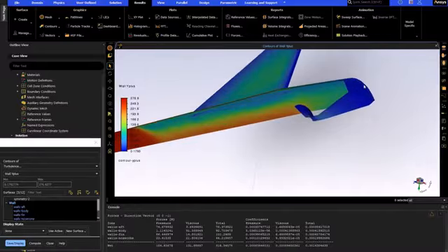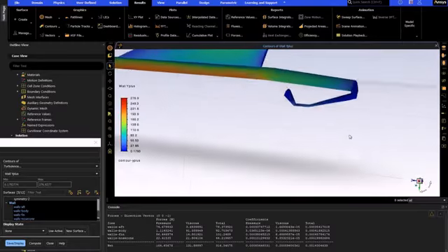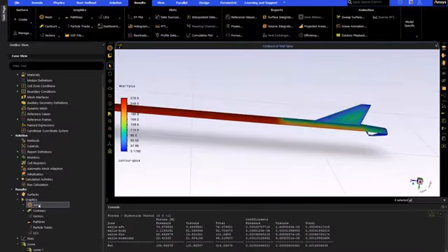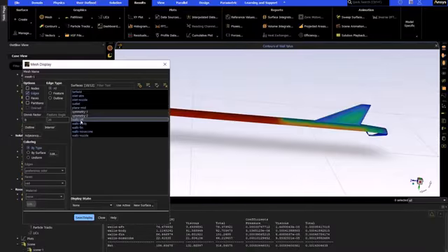For drag predictions, wall models will give a reduced accuracy for Y+ between 30 and 300. To improve drag predictions, the model must be remeshed with a smaller first layer height, giving Y+ less than 5.